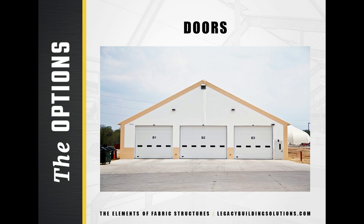Jack beams are horizontal transfer beams that carry an intermediate frame that has had its sidewall column removed. The load is then transferred to the adjacent frames and their corresponding columns. Using jack beams allows the building to be safely supported with fewer vertical members. This creates extra wide openings, 20 feet or more between supports. Jack beams can be used to create sidewall entry points to allow for even the widest equipment, including mining trucks and heavy construction equipment.